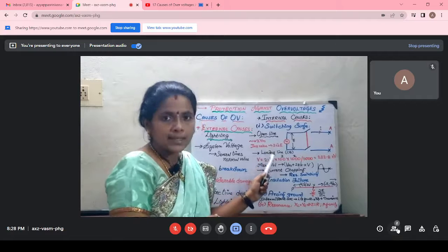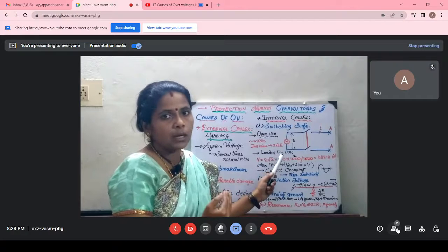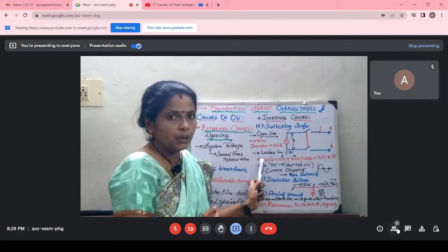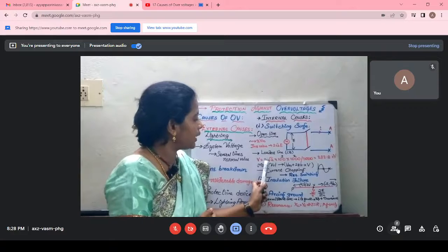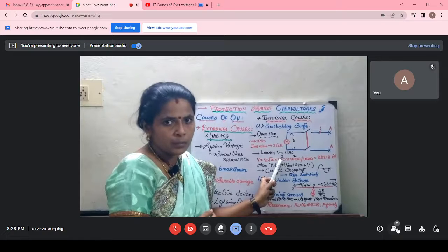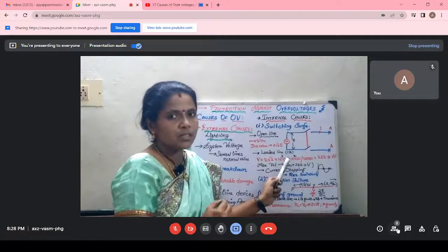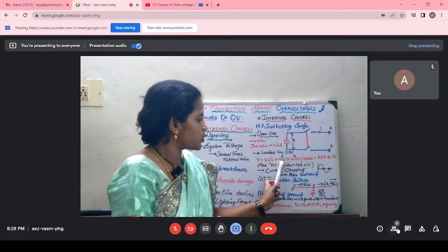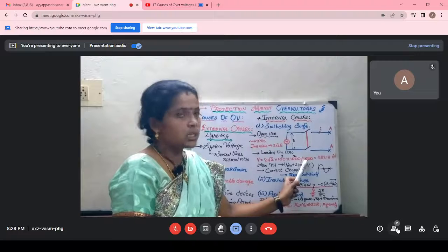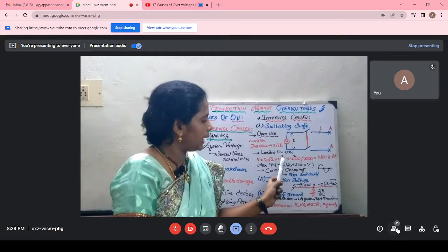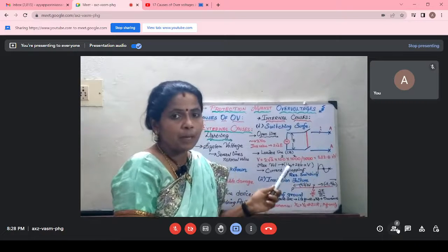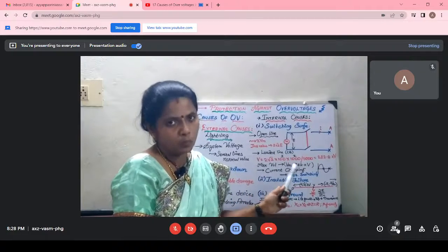Now we will analyze the loaded line. What happens if the loaded line is considered? What is the formula? V is equal to I into R. Already we have seen it will rise to the value of 2 into root 2 times E. Now I am going to write it in terms of current and impedance. Here I have considered a small problem where the current is 100 amps and the impedance is 1000 ohms. Since it is represented in kV, after doing the calculations, it comes out to be 282.8 kV, just for a simple example of 100 amps and 1000 ohms.